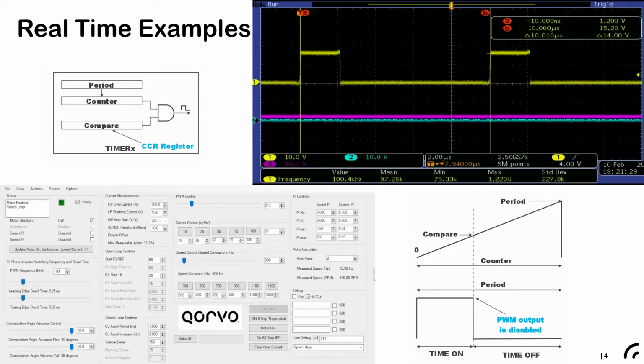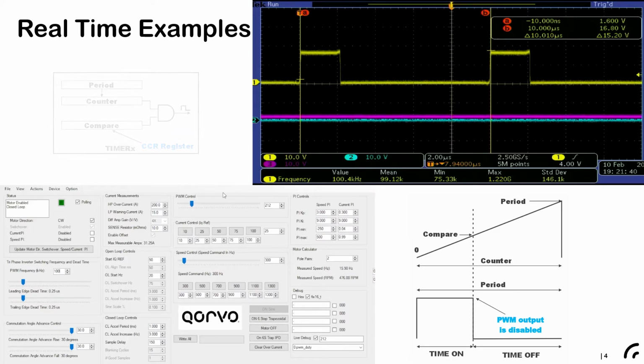output. So if you look at the scope, what you're going to see is that the time that it goes high, that's the beginning when we start counting as 0. And then when it goes low, that is the moment when we hit the CCR. So when I change this number, let's say I put a 200 in here, that's 20% duty cycle because it's going to count up to 1000. So 200 out of 1000 is 20% duty cycle. That's what the CCR got updated to.